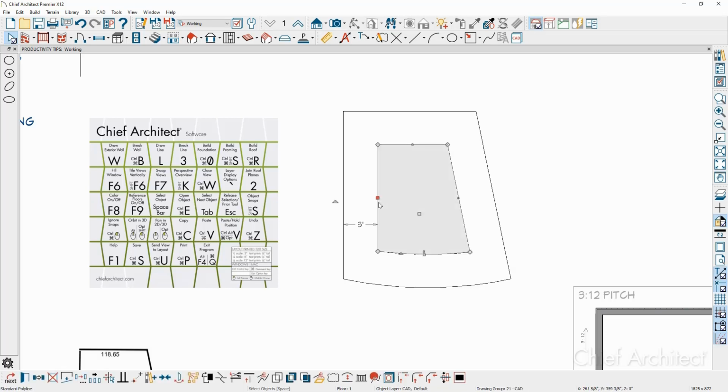If we turn on our temporary dimensions, it's exactly 36 inches in. If that were very large and you wanted to do several concentric copies of it, you could do that and it would pop in those 36-inch increments. So that's holding the letter C down.